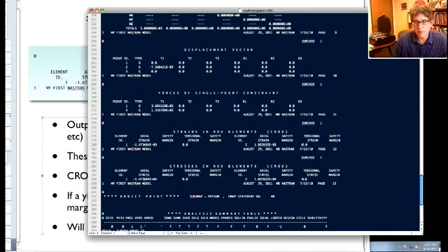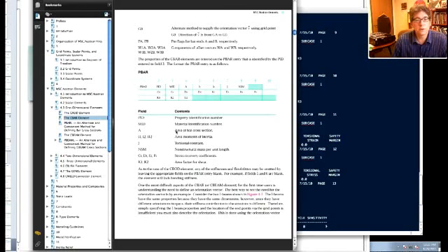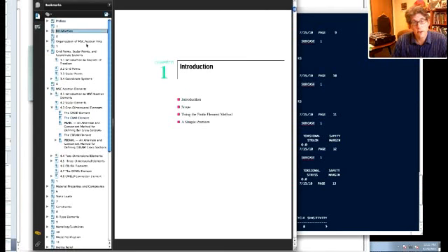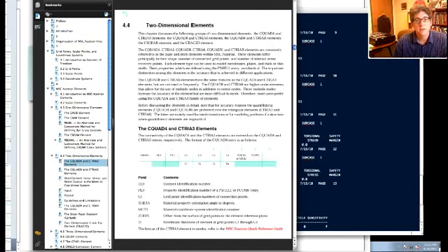Again, I also recommend looking through the Nastran reference manual, the linear static user's guide. Whenever you start doing these homeworks and developing these Nastran files, always have this open. It's a big help. We'll be looking mostly at the Nastran element section, and that's where you'll be most of the time. If you're doing 2D elements, you might look at the CQUAD4 elements and the CTRIA3 elements, and look at the sections here. Okay, you can see these are actually the forms of the inputs. All right.